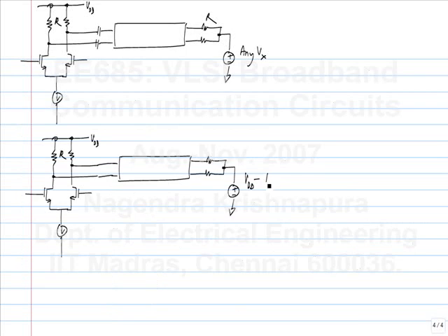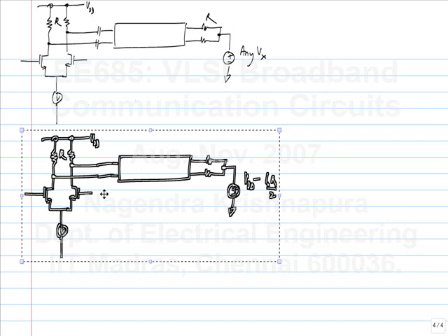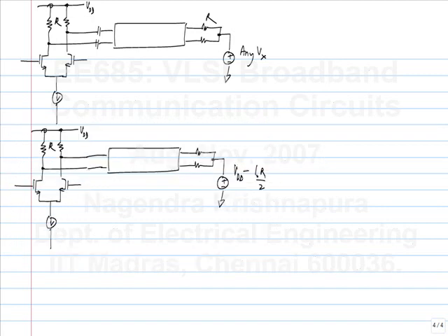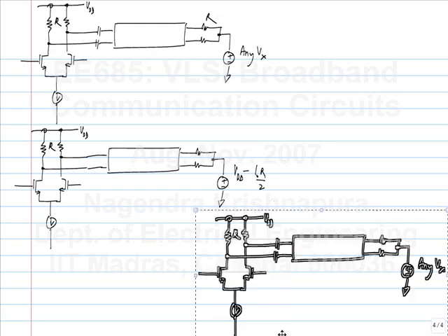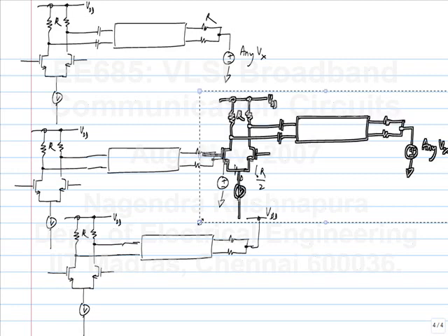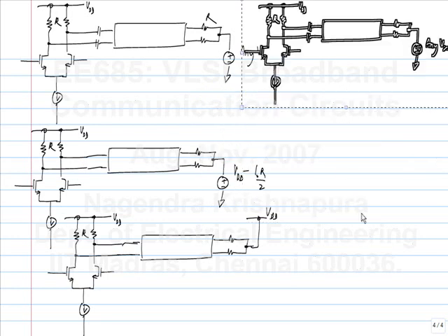So the other thing is, okay, I don't do AC coupling, I do DC coupling, but then here I connect it to exactly VDD minus I0 R by 2. So that is another scenario. So alternatively, I can also connect this and tie it to VDD on this side. Essentially that does it.